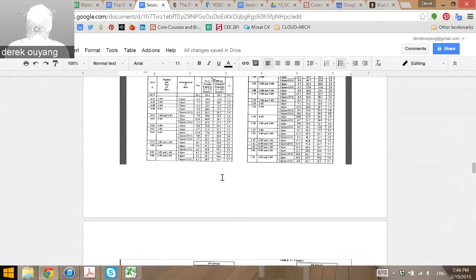And then you check if it's tension controlled, right? You guys have been doing that most of the time. And then tension controlled or transition or compression just changes your phi factor. That's the only reason you're doing that, right? So then you get all the way to the end of that, and then you have Mn, my capacity. You already know Mu, right? That was just the loads of the structure, what it has to deal with. Your Mn is your phi times any one of these, but usually you put As Fy here. And then you're doing the lever arm, which is going to be your depth all the way to the top there, minus whatever A was divided by 2, right?